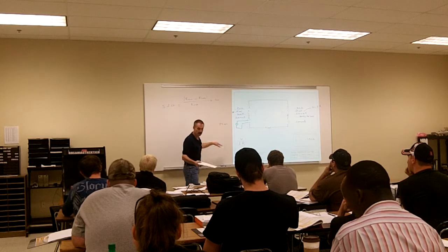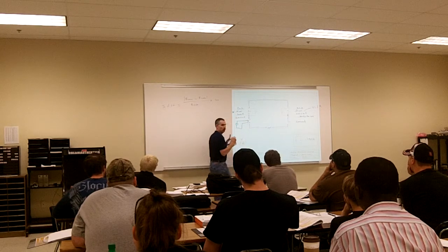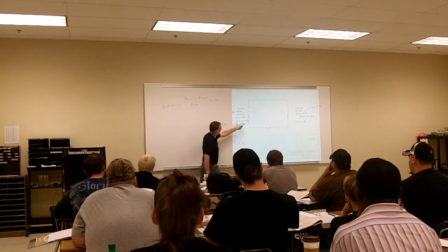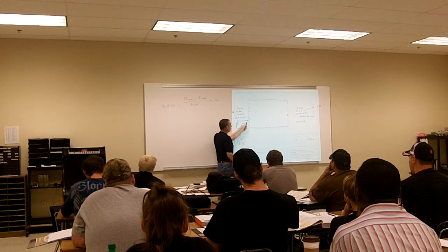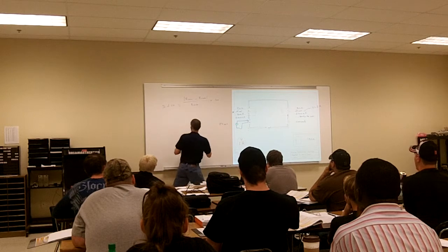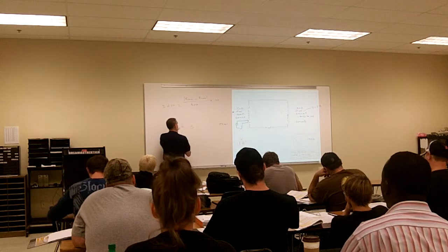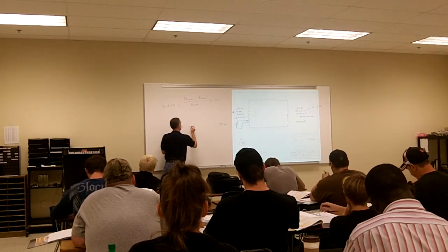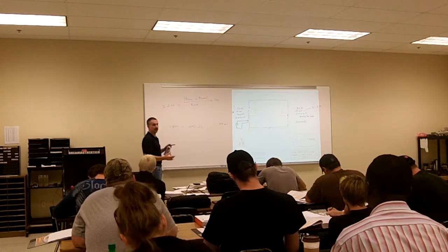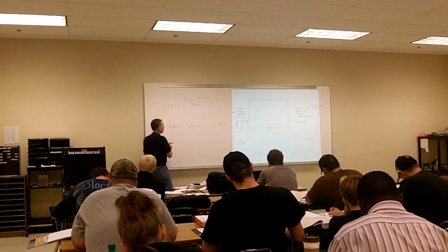It's an open. That means if that fuse is an open, that fuse is no longer in there, right? If it's an open, I have no current flowing through there. So if all of a sudden I measure 24 volts going across the fuse, that means my fuse is open, and I have no more current going through there. Because that open, this is a good thing to write down, is equal to infinity ohms. As much resistance as I can have in there. I can't have any more resistance than an open. So I have a very large amount of resistance.